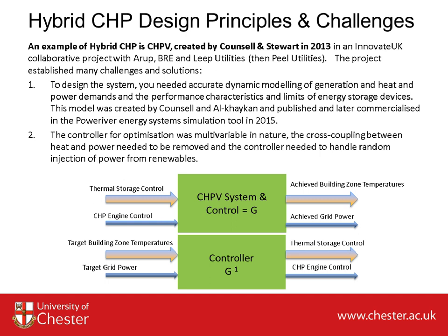Perhaps something you may have heard people talk about energy twins. We developed an energy dynamic twin, minute by minute heat and power, so that we could actually design the controller virtually before trying it out on the system. What we also need to do is use that model to work out how to size components in the system. You can't size these systems statically and optimize them. So you do need a dynamic model in order to be able to optimize the sizing of such a complex energy system.